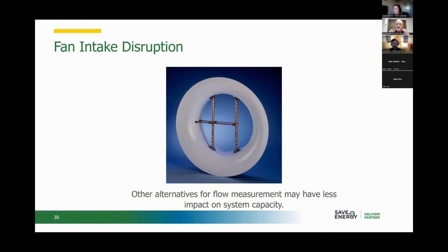And I did some testing in the shop with this one day and found very quickly that when these guys start putting things like this into the inlet cones, it kills the performance of the fan. I mean, you'll knock 10% of your flow capacity off your fan. Maybe not as much if that fan was a bigger fan, because that's sized for, it's kind of small for that particular fan.